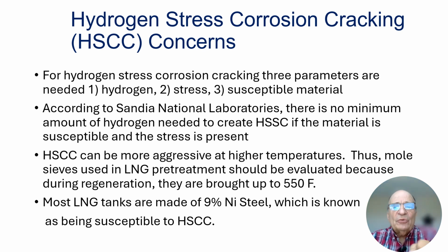So this steel or whatever else it is that is now under stress has porosity in it. It has little gas pockets within that steel, and that becomes a weak point. As that steel stretches further, that hydrogen follows that stress point all the way until eventually you have a full crack that takes place. You need to have also susceptible material.